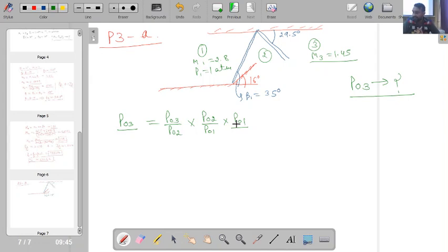Okay, so that is the reason why, in order to find P02 by P01, we have to do some more exercise. So how can I find P02 by P01? I can write P02 by P01 as nothing but, first I can calculate P02 by P2, because this relation is generic, available to us, and not specific to the normal shock wave.